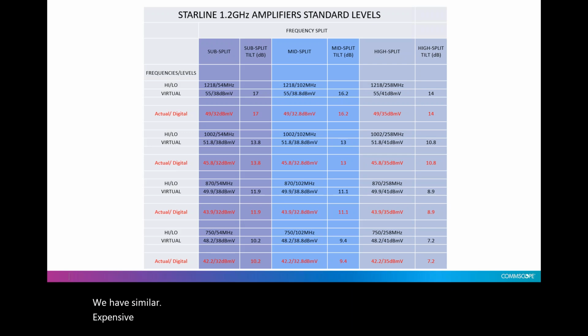I would like to also comment that setup becomes extremely important, and the reason is because OFDM is an extremely robust signal, so there's a high likelihood that operators, even though they might be limited to a gig or may only show bandwidth up to a gig, there's a good chance that they'll start putting OFDM carriers higher than that. If your setup is wrong, then you'll start getting overdrive in your amplifiers, or maybe you're just low on signal because the tilt's not right. You're not getting enough gain at the high end. So setting up and making sure your response is linear between your high and low carriers is very important.